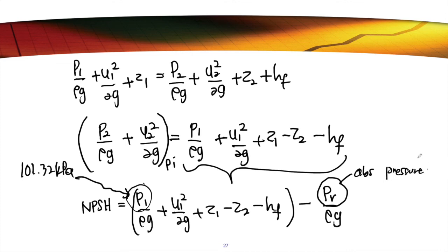But for chapter 8, we will zero this term since it is P atm, or you have to minus PV. You want to zero these terms, that is okay, but for the PV you have to do PV absolute minus 1 atm. You have to make it a gauge pressure. In the question PV given is always in absolute pressure.